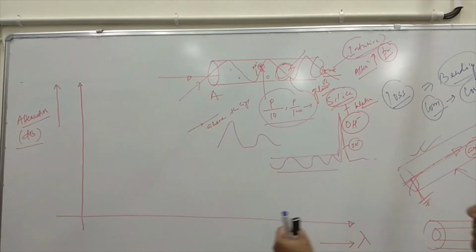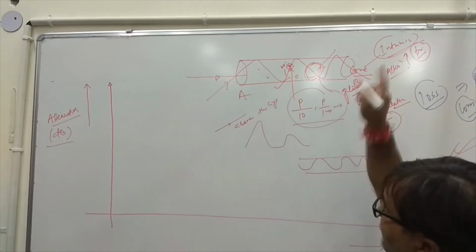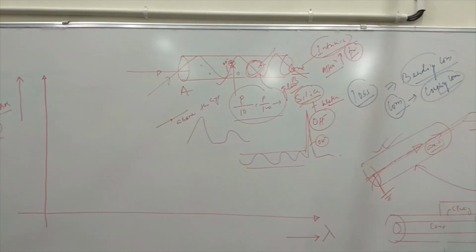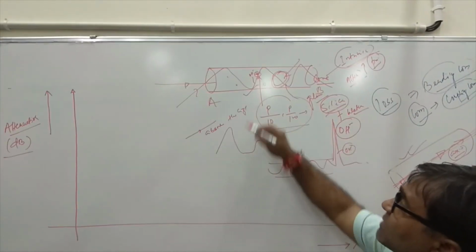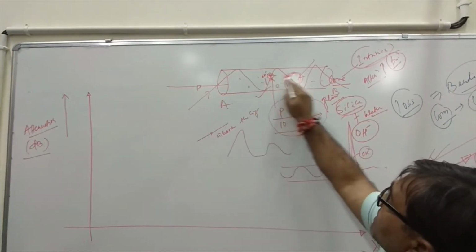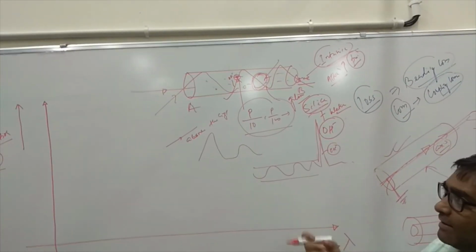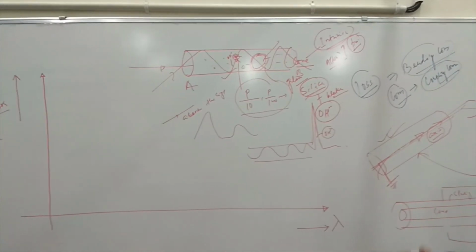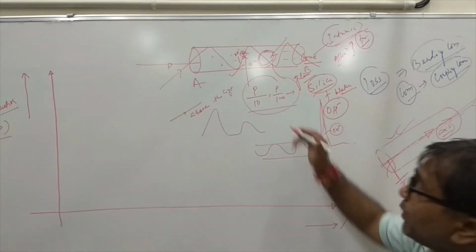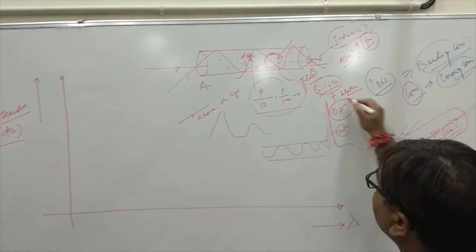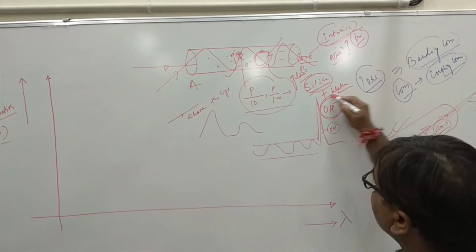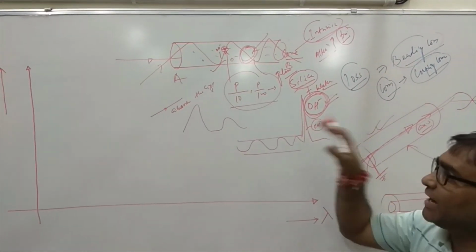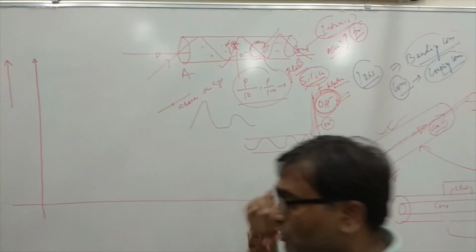So due to intrinsic properties, attenuation will be high. At the same time, if OH minus appears across this silica, because sand absorbs water molecules very easily and they are very difficult to segregate, OH minus ions are again a very dangerous factor that appears along the fiber in the form of attenuation.